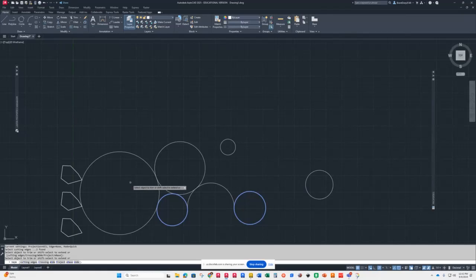So depending on what you're doing, when you go into trim, you may want to be more surgical, and I will be that way when I'm showing you how to do some of the assignments. When you're done, hit enter to finish out or the space bar. And like I said, if you just go into trim, you can just start getting rid of stuff left and right until you're left with the shape that you want. And go from there.